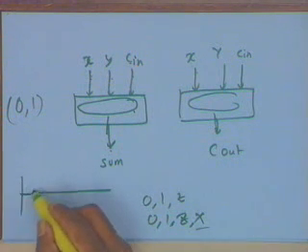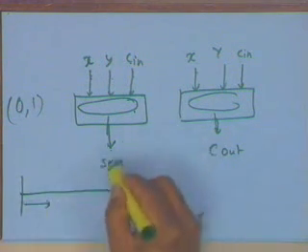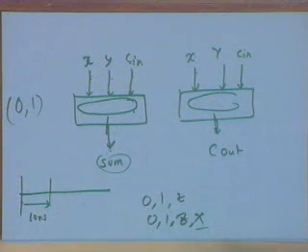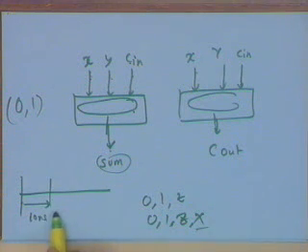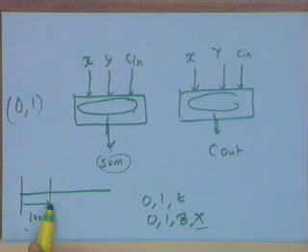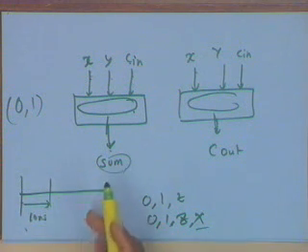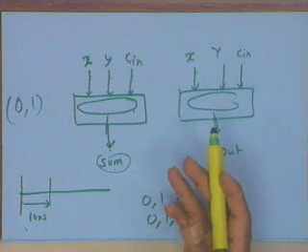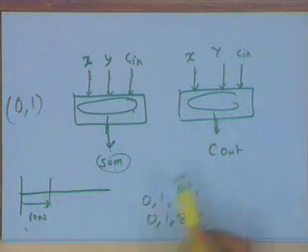What it means is, I make an evaluation and assign to this particular sum after 10 nanoseconds the value that I have got. How the simulator proceeds we will see later, not in today's class, but when the simulator actually comes to this particular time, which is 10 nanoseconds from the present time, then the sum will actually get the value that we have decided.